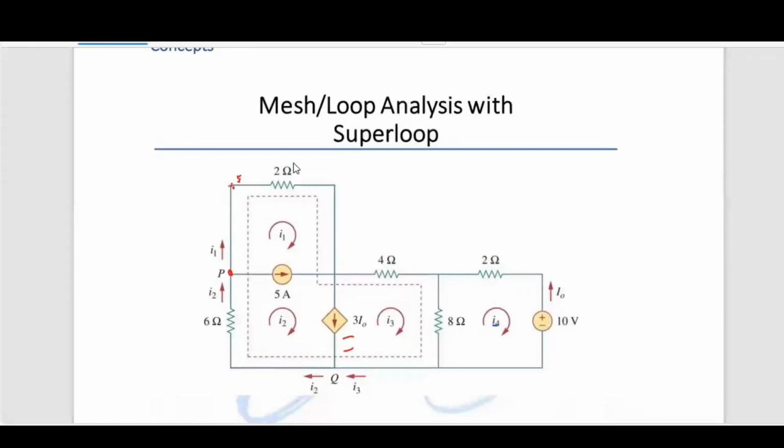So you go in here to here, then up here, here, and I'm going back to it. If they call this A, B, C, D, I'm back to A, right? So if I do any loop A, B, C, D, back to A, right? Watch it. So if I go in from A to B, nothing happening, that is okay. So I go in from B to C. So watch it. I go in through a resistor. So it'll be minus 2I1. Alright, so that happens. From B to C, we have a drop. Then we're going from C to D, we have nothing again.